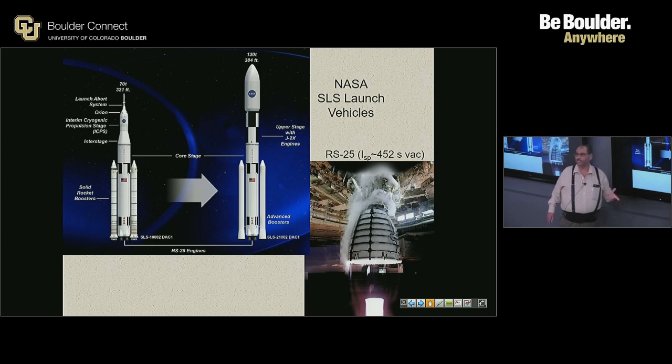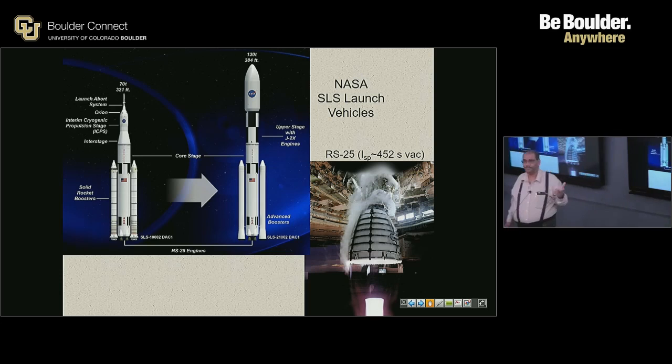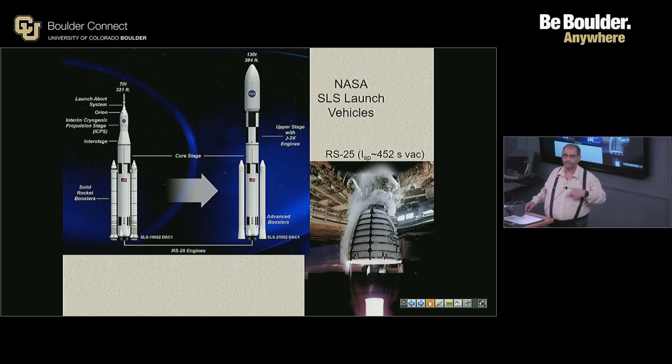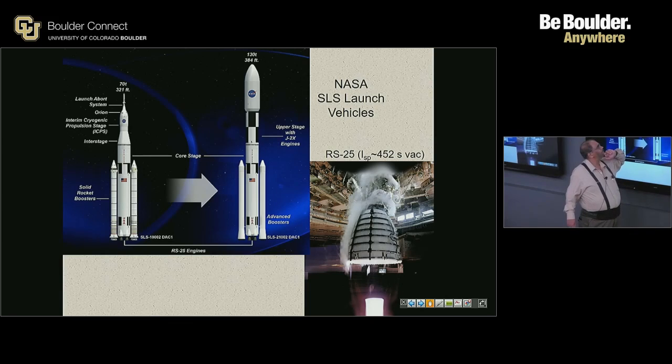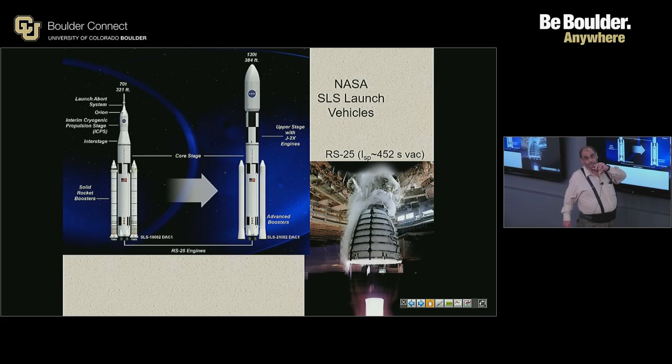But they have also tested the J-2X. They actually rebuilt the J-2. They took the blueprints, improved it, the turbopump, the nozzle, etc. So J-2X has been tested, works beautifully, okay? But it's on the shelf somewhere. So they're going to use that later. This one has a capacity of 130 metric tons. It's as much as the Saturn V, initial version. The final version, Apollo 15, 16, 17, was 140 metric tons. So that is capable of building the international lunar village if we decide to.